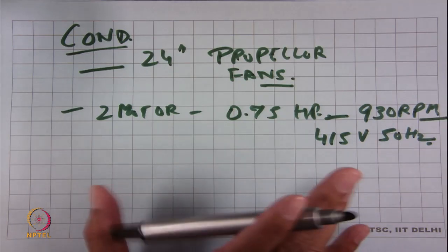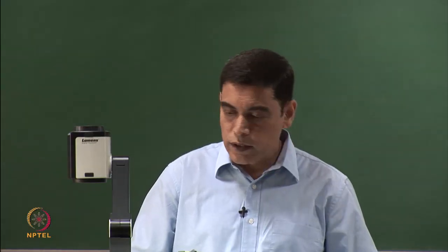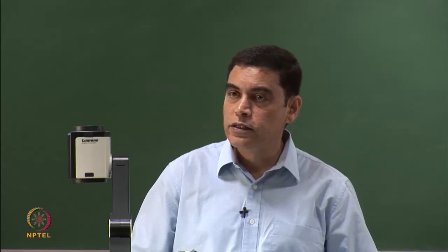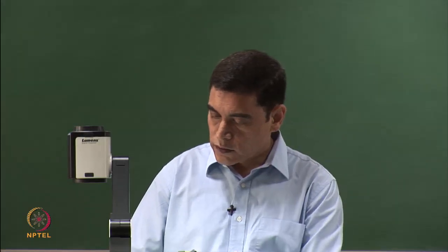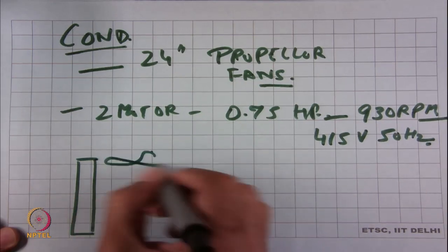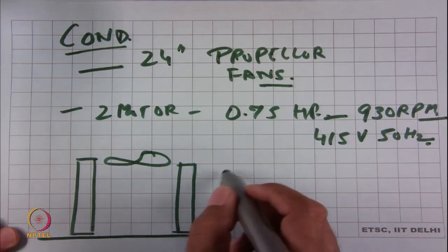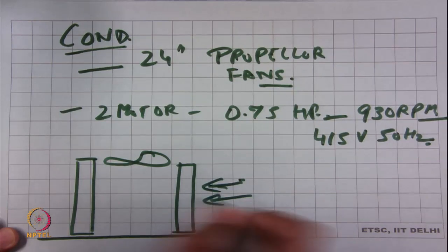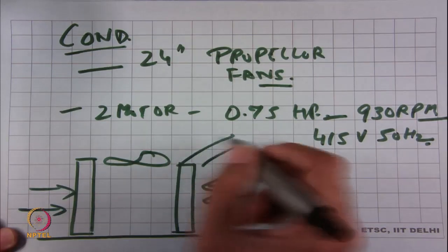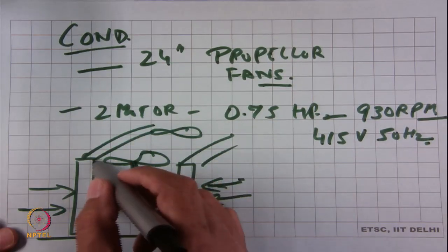So, we made a selection on the compressor, the evaporator fan, the condenser and the blower. On the condenser, if you want a little more detail, the length between tube sheets was 1320, and the height was 22 tubes, effectively 22 inches, vertically. The condenser configuration would have a fan over here and another condenser on this side, and this would be the base. Ambient air comes in from both sides, and looking at it longitudinally, there would be another fan at the back like this, fed in towards this, and mounting was a flange mounting.